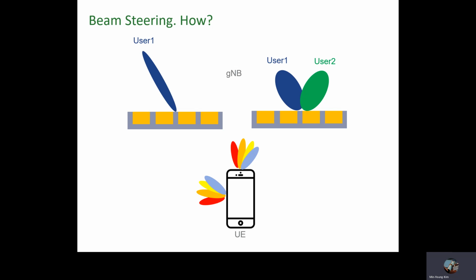The direction the signal is sent is calculated dynamically by the base station as the endpoint moves, effectively tracking the users. If a beam cannot track a user, the endpoint may switch to a different beam. This granular degree of tracking is made possible by the fact that 5G base stations must be significantly closer to users than previous generations of mobile infrastructure.